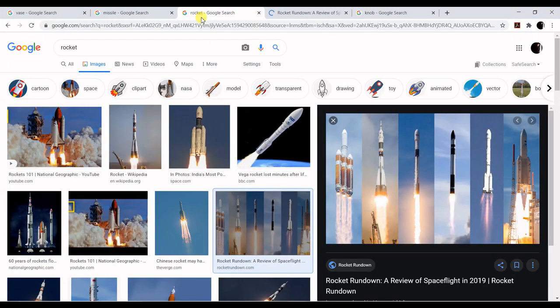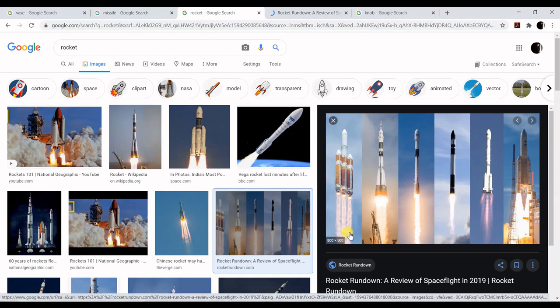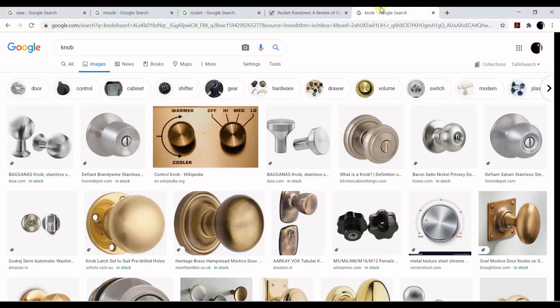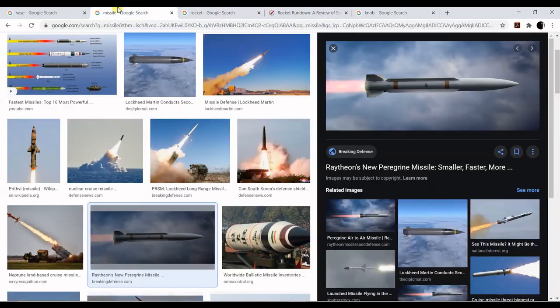In order to create this kind of shapes or designs, we will be required to work with the Revolve command. What are the other options we can see? We have a doorknob over here. This is also circular in shape, but there is a variation with respect to the diameter. We can create it using Revolve, so don't worry about it. But if you cut the knob or this kind of axisymmetric component laterally at any location, the cross section you find will be a circle. For example, in the case of a wing, you will find an aerofoil shape if you cut its cross section.